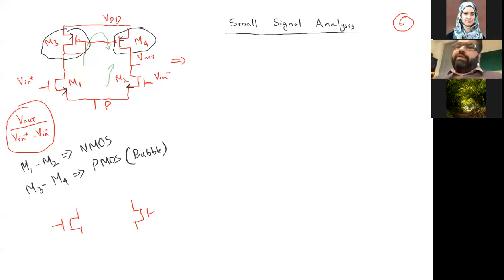But at this moment, I will just draw the architecture, how the PMOS architecture will look. For example, again I'm writing M1 and M2, but these are the PMOS now. So these PMOS are your input ones. These are the two sources again, and the sources are going to be connected to the highest potential. So here is the highest potential, and the current mirror are NMOS now. So here NMOS, and this is NMOS.